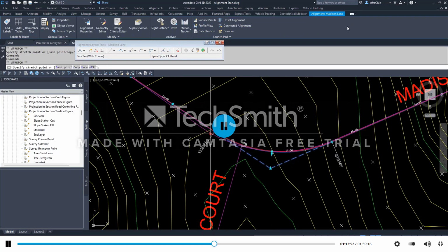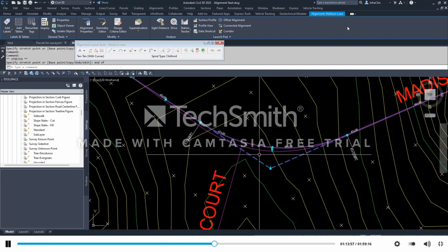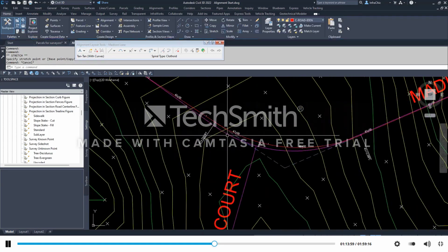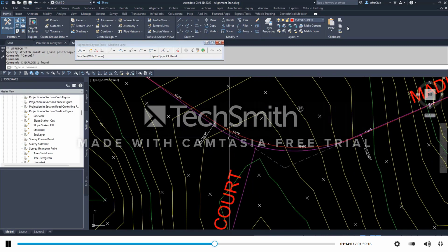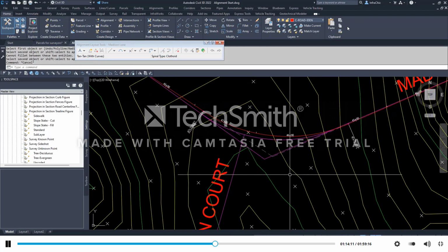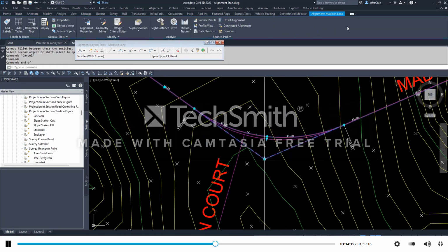And that's what's interesting, you can't get it on the money. Sometimes it'll drive you nuts. It really will. Now, if I really want to know, I would take my polyline that I didn't erase. I would explode it, and then I would fillet it with a 0 radii. I grab here. I grab there. That's where my PVI should be. That's the cheat method, by the way. Bing. Okay. I got that lined up.